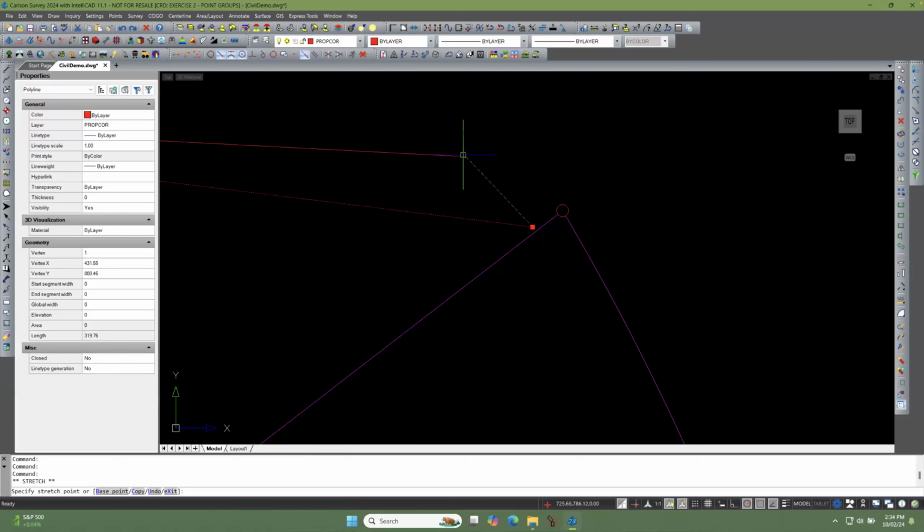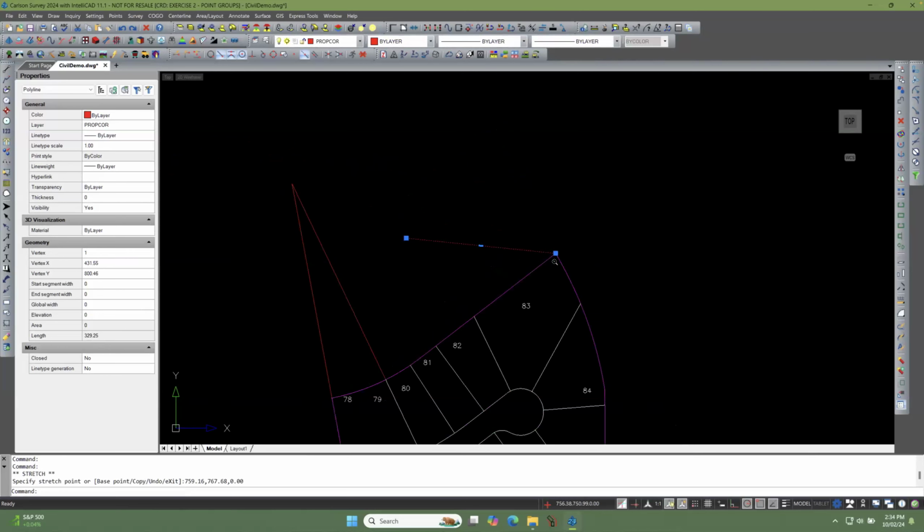But if I grip, and I'm just clicked in it with the left mouse button, I'm moving it around, and I hover, the snaps are back on. Because shift right click only affects that one particular click. All right, so that's selected. I will turn it off.